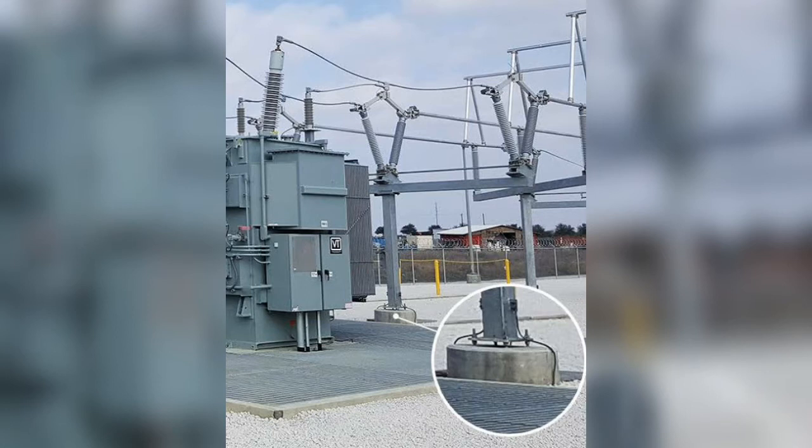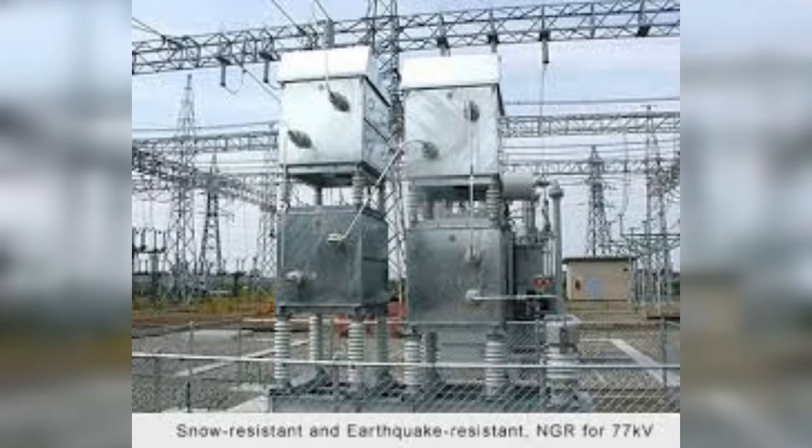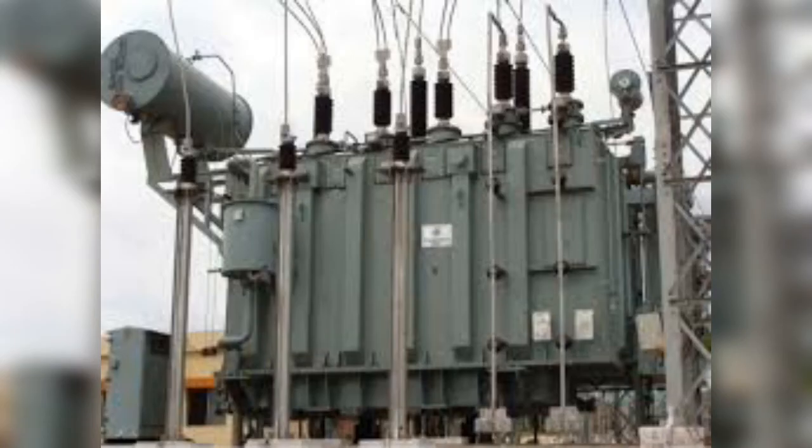Temporary current goes in and it will be grounded, and the current will run toward the ground, not through the body of an operating worker or an engineer. It is often assumed that any grounded object can be safely touched. Before you operate anything, you are required to check their grounding properly.